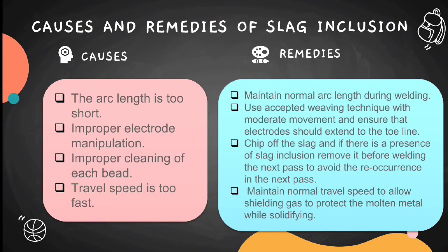For the causes, we have the arc length is too short. We also have improper electrode manipulation and improper cleaning of each bead, and lastly, travel speed is too fast. To solve this problem, we have these remedies.